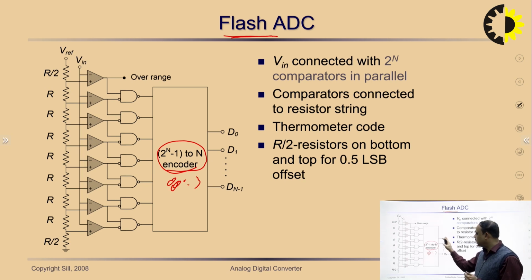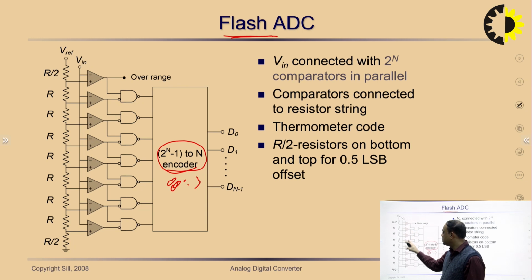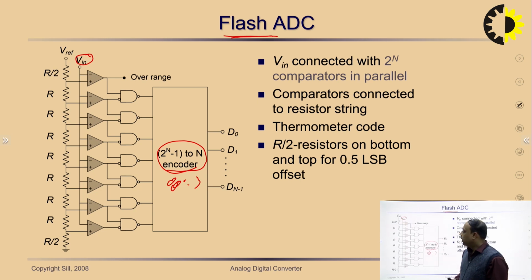The 8:3 encoder circuit provides the 3-bit code at the output, and has 8 input pins from 0 to 7 as the input. Now for each input pin there is a comparator, and the input reference signal is divided into 8 subcategories over here, as we can see. An R and R by 2 ladder is over here, and the input signal is provided on the second terminal of the comparator.